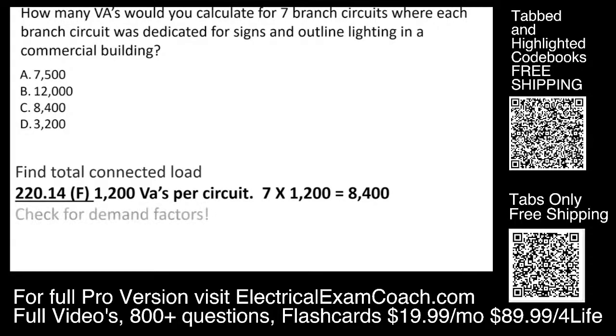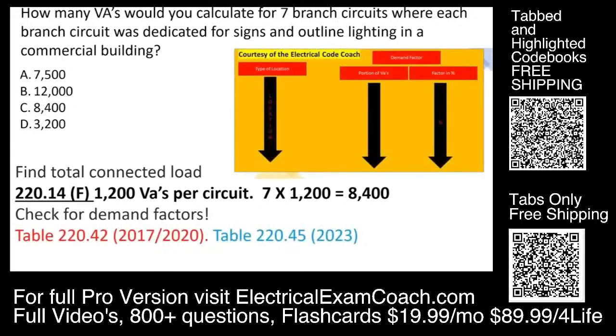Now, let's check for demand factors. Anytime you're doing commercial lighting, you're going to go to table 220.42 if you're in the 17 or the 20, or table 220.45 if you're in the 23. Same table, different title.